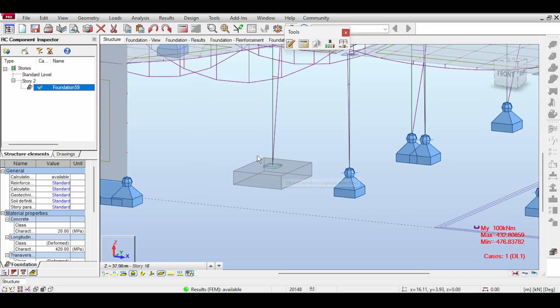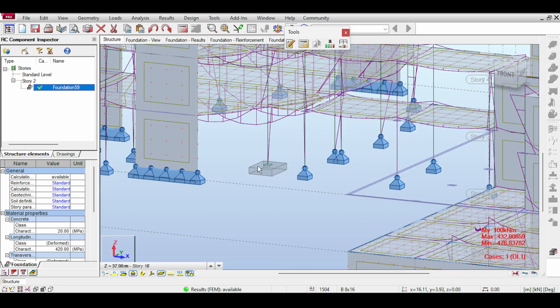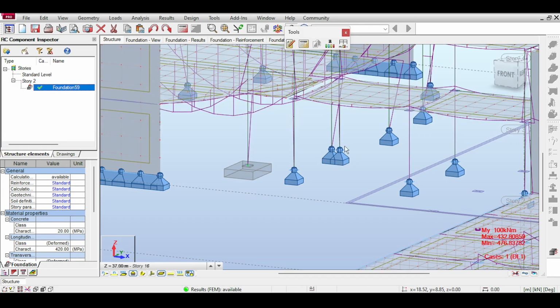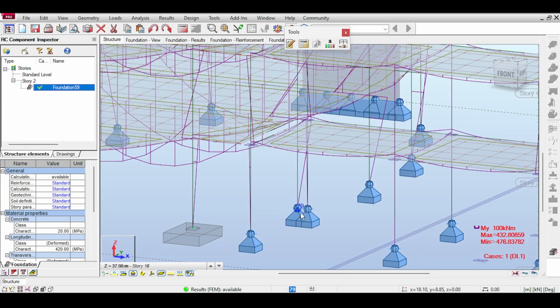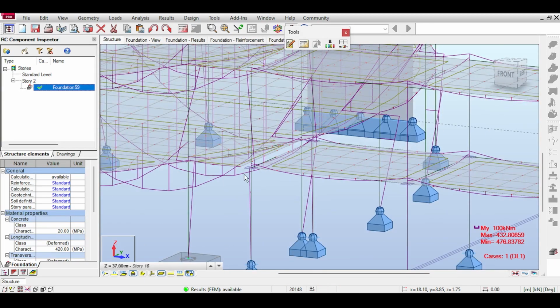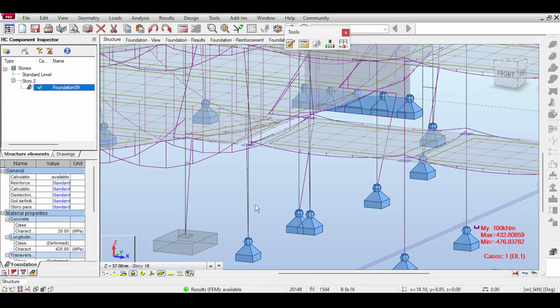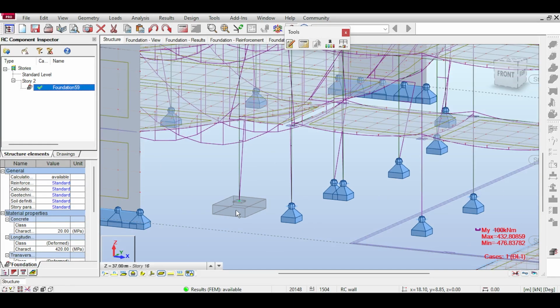And you might want to limit some of those distances in the foundation, just in case the foundation is neighboring or has some geometrical considerations that you need to take into account. And I will be talking about this in a moment, because those are 2 separate structures. You have a bridge structure and the structure here. Because there is a structural joint, we will have to have 2 foundations here. What I'm saying is that it's a nice touch in Robot that if you go back to structure and just hide and show the supports, you will see your designed foundation.